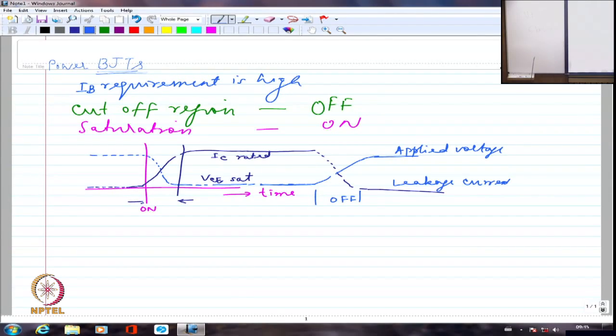But turn on and turn off losses are there in almost every device we talk about, whether it is a thyristor, diode, IGBT, BJT or MOSFET, anything. We are going to have it. So the lesser this duration is, the smaller the overall energy loss is going to be. That is why we are also looking at reducing the turn on and turn off time, from the point of view of improving the frequency of operation and the overall incurred energy loss.